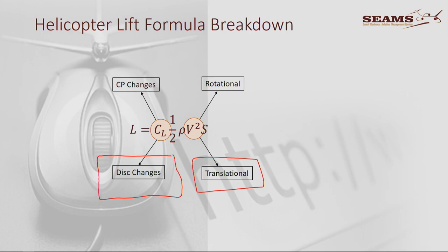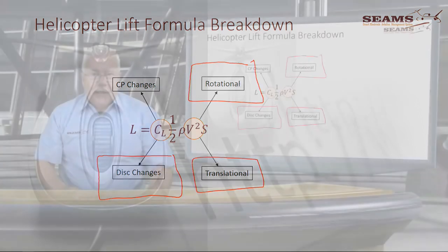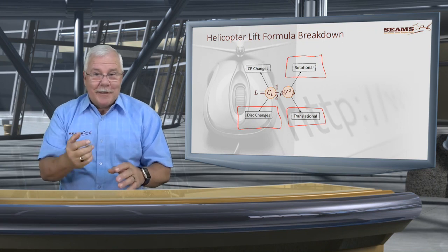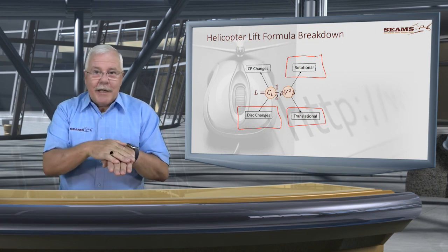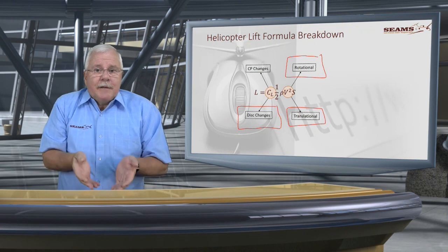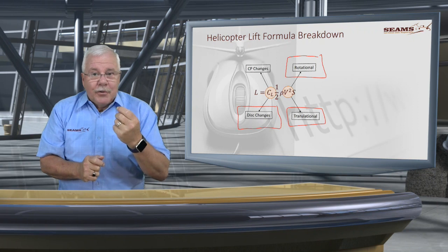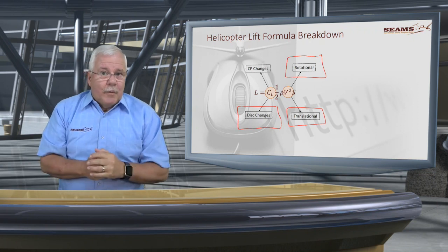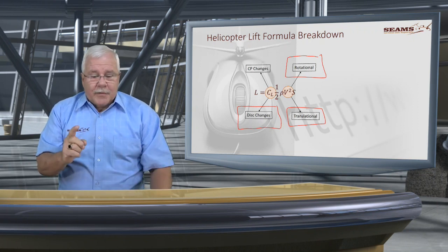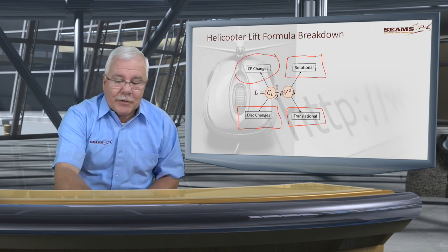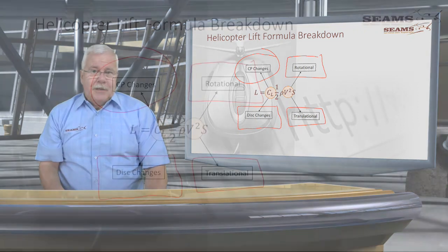So let's just say, from a helicopter point of view, we've now got extra, because remember the blades are also rotating, and therefore there's rotational energy as well. This is a rotary wing, and the rotary wing also creates a flow. In other words, we can lift off straight into the hover. That is still flying, and for that you need lift, or if you wish, thrust. So how do we manipulate up and down? Obviously, we've got the collective pitch changes that we can do.